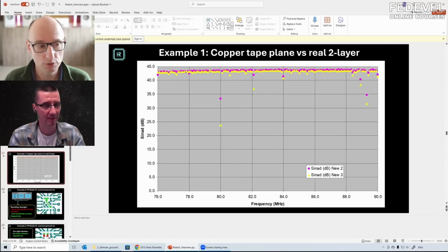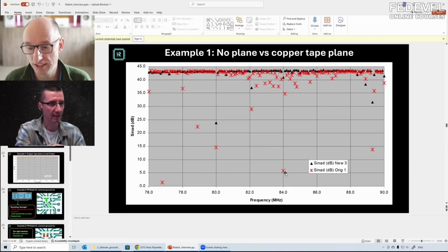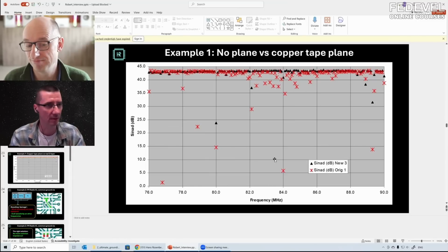Yeah. What's good to realize is where did this interference come from? Well, this radio had an analog front end and a digital back end. So it had clocks. And what you're basically seeing here is all kinds of locations where harmonics from these clocks fall. Look, this one falls exactly on 78 megahertz. This one exactly on 76. Oh, you are right. It looks like exactly 84. Periodic. Yeah, it's periodic. And so these are basically the harmonics from clocks, which are transmitted all over the place